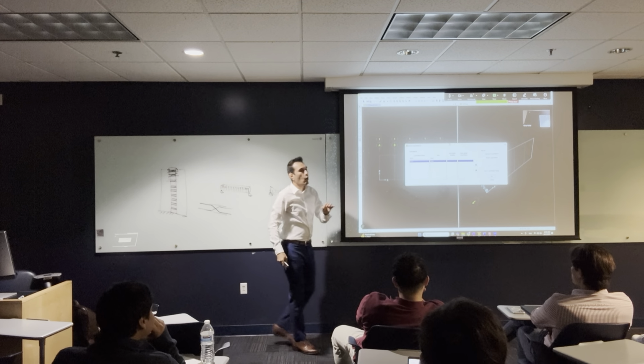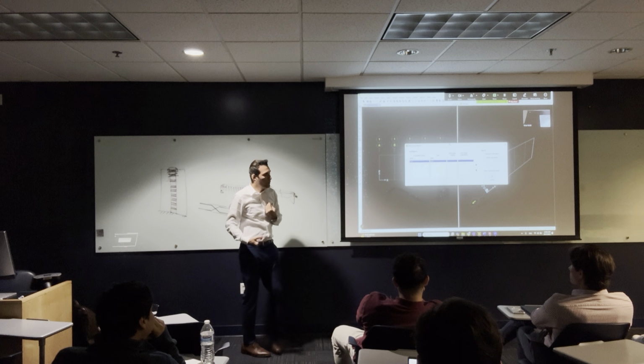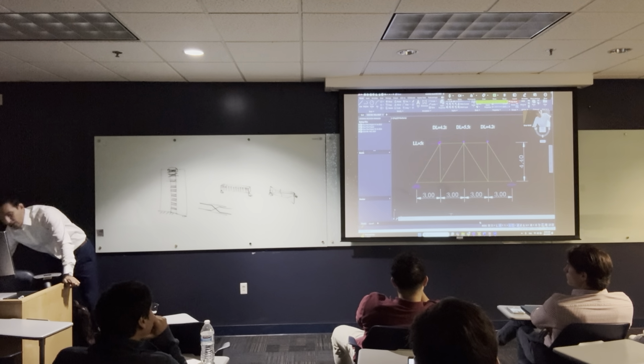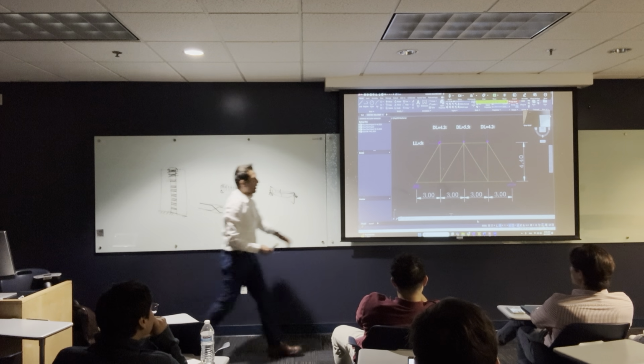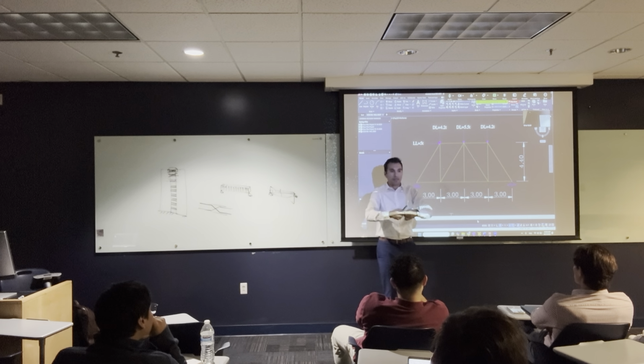But let's say you don't want SAP 2000 to calculate this for you. What should I do? In our problem here, I don't want SAP 2000 to calculate loads for me. Because if I let SAP 2000 calculate the load for this, it is going to act like a simple beam, and it's going to have a bending moment.